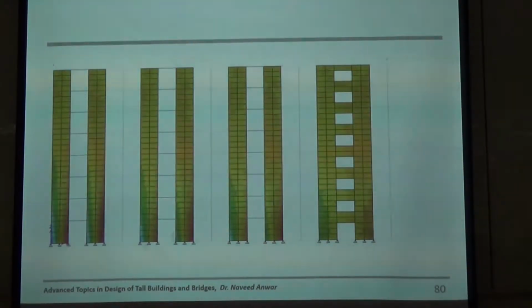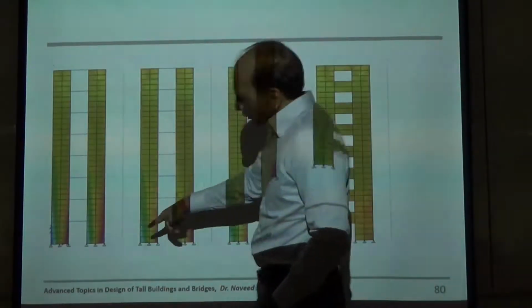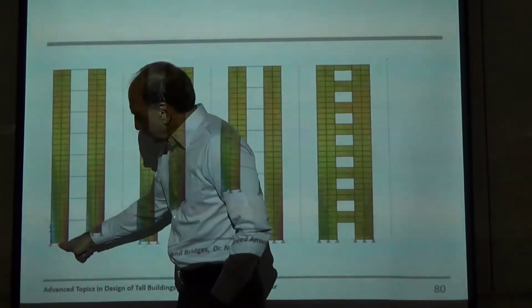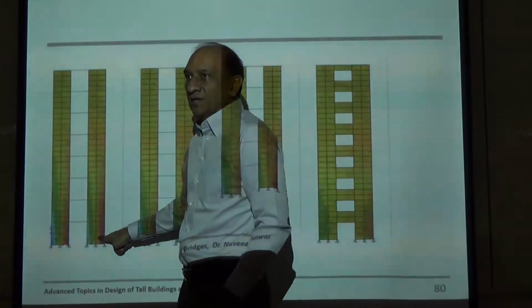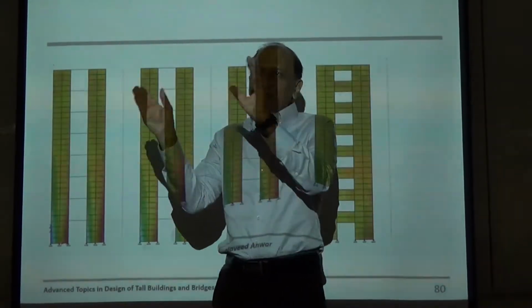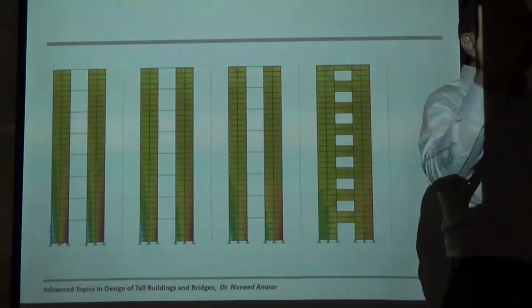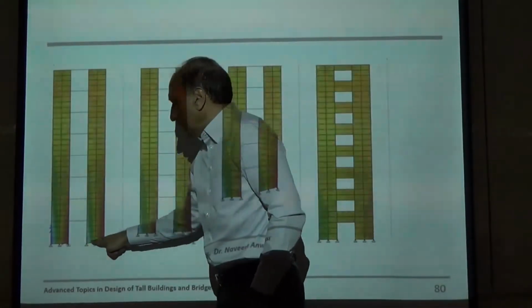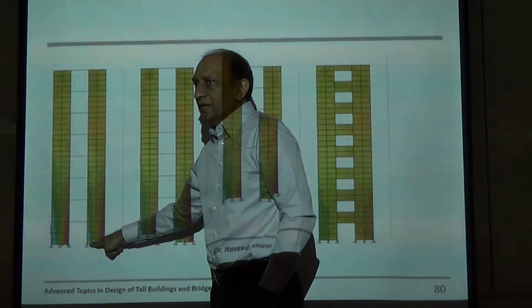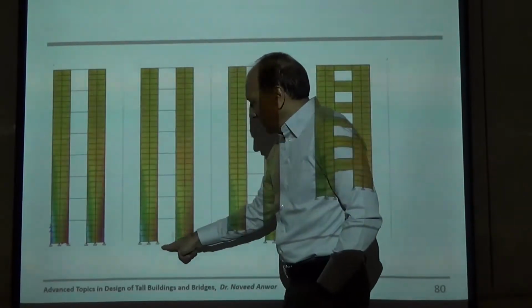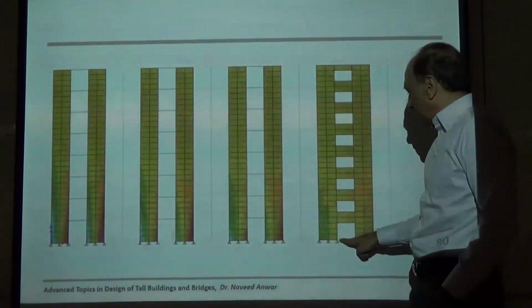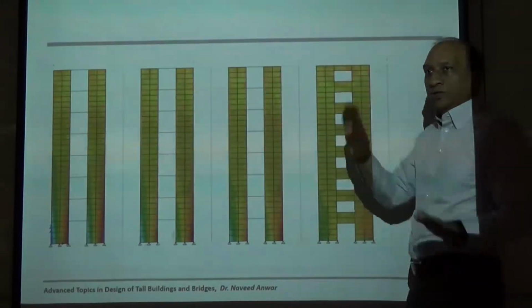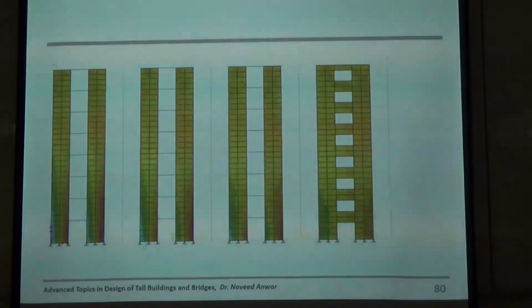It's not so clear on your screen, but you can see the stress is also different. Here, if you can see a little bit, tension, compression, tension, compression. Which means each wall is bending as if it was an independent cantilever. Each wall has tension and compression on each side. Here, a little bit less. Here it is disappearing. Here, tension, compression. So the two are acting together now.